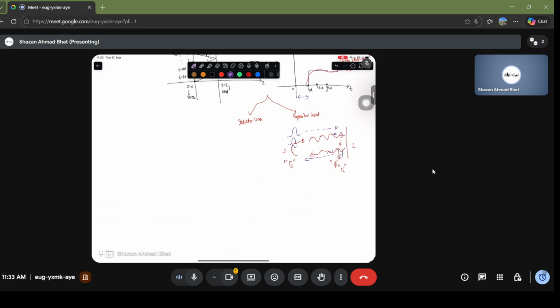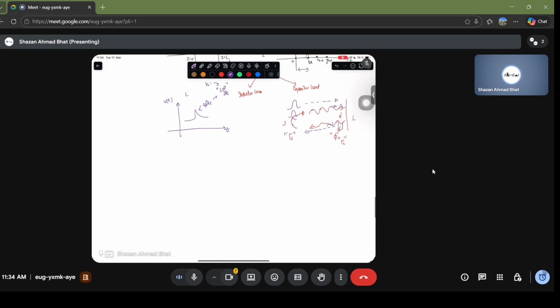Now you talk about if you had different types of loads, let's say you had a capacitive load or an inductive load, then how essentially the voltage waveform is going to behave. So if you have an inductive load, most of the time the voltage will be flowing like this, and then there will be a sharp peak, there will be a spike. And this is mostly because of the L dI by dt sort of kick because of the inductance. So the voltage of the inductance is L dI by dt because there's a dI by dt term. So there will be a sudden spike in the voltage because of the inductance effect.